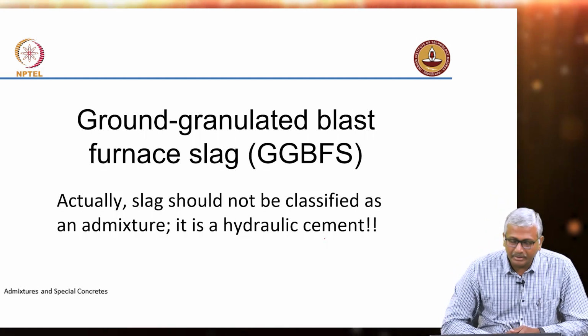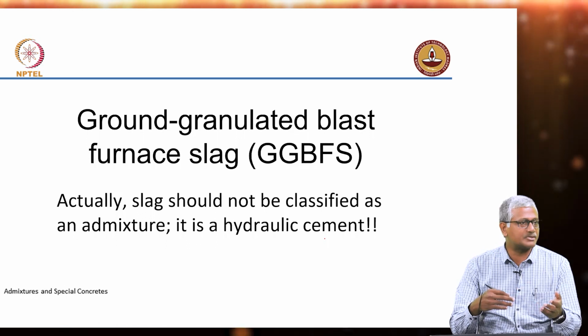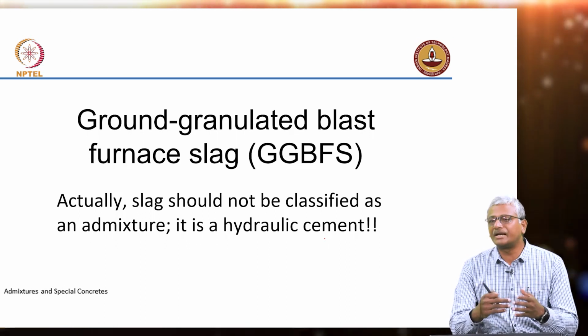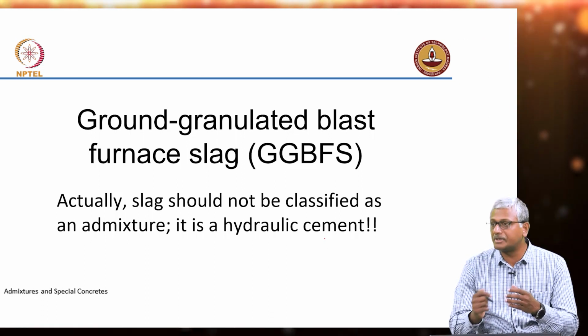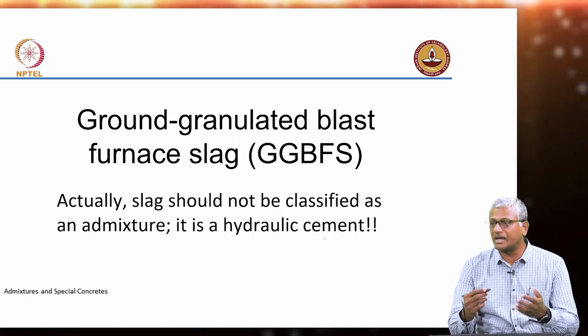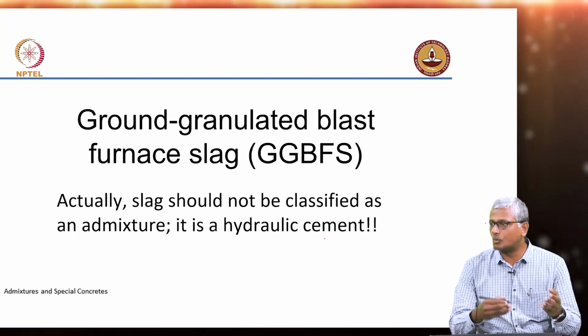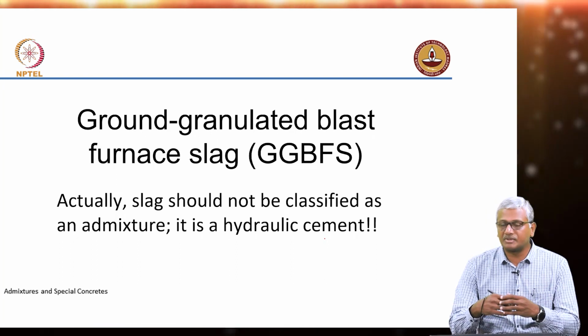Right. So, most of the aspects that we discussed about resistance to chemical attack and corrosion and carbonation, a lot of that will sort of repeat in our discussion of other chemical additives or other mineral additives also. But nevertheless, we have to understand the basic chemistry of these materials, as to what goes into making the system different from a plain Portland cement based mix.